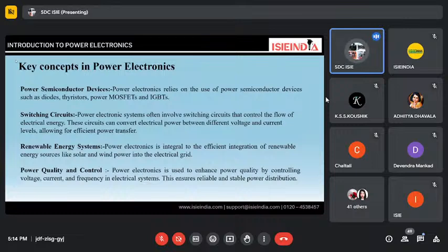So at a certain point, you can accelerate the motor at different RPM, and the torque will be different. We will see that torque characteristics and the RPM of the motor are inversely proportional. So at different acceleration throttle positions, you can do that. We have full command with the help of power electronics only. It is useful for two-wheelers, three-wheelers, and four-wheelers, wherever there are connections of the electrical controller and AC-DC driver circuit. The controller is a hard part of an EV. Without the controller, you can't run the vehicle.